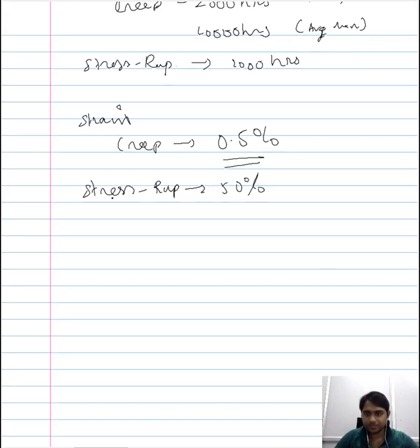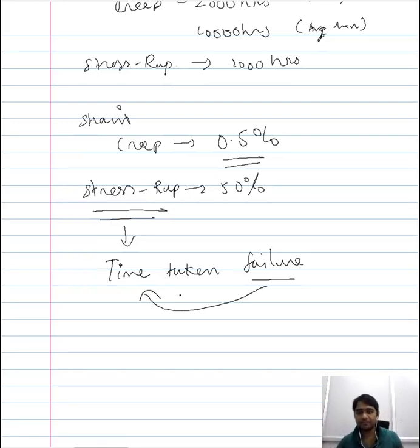Now, the reason for performing this stress rupture test is to understand the time taken for the overall failure of the material. So we want to calculate the failure time. That is the primary focus of the stress rupture test, and that is the reason why we see such a significant difference in the consideration that is made. Even though this test is performed in a framework similar to that of creep testing, even though we maintain high temperature and plot strain against time, even though the stress rupture test speaks largely of time dependent deformation, we increase the stress in order to understand the time taken for the